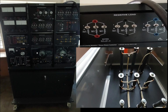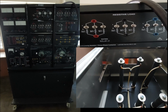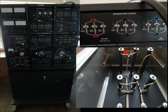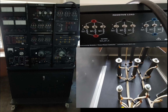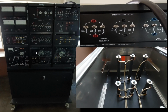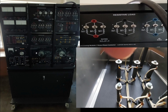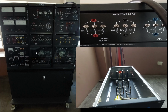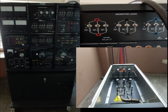Six safety banana jacks on the module front panel provide access to each resistor bank. The resistor banks can be connected separately for operation in 3-phase circuits. Also, the 3 resistor banks can be connected together for operation in single-phase circuits. The resistive load is commonly used in conjunction with other basic loads, like the inductive load and the capacitive load, to experiment with the effects of the different types of load on a circuit.